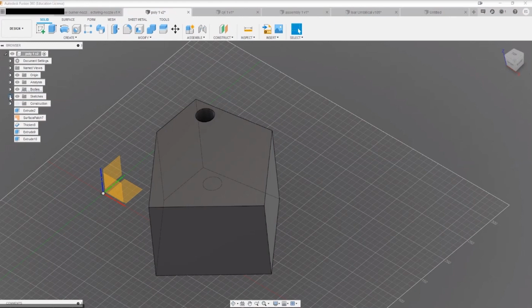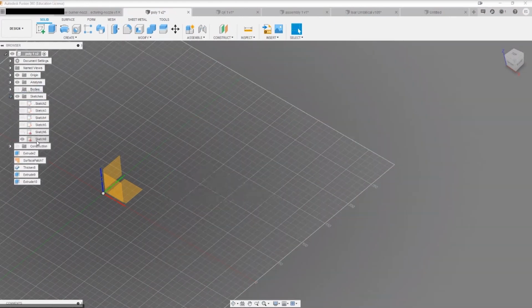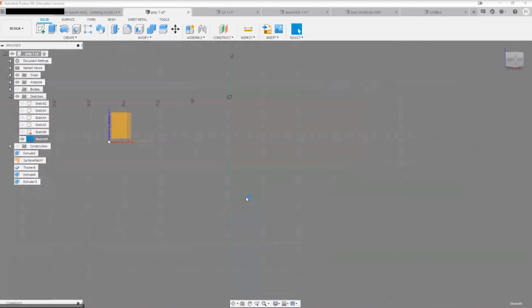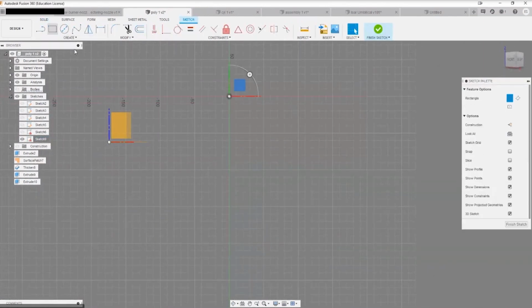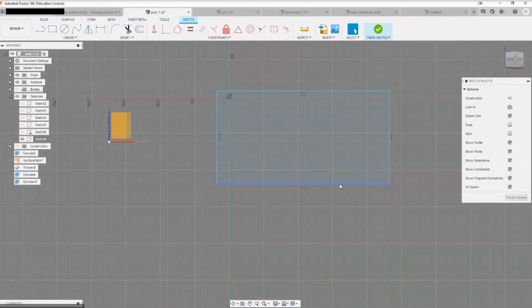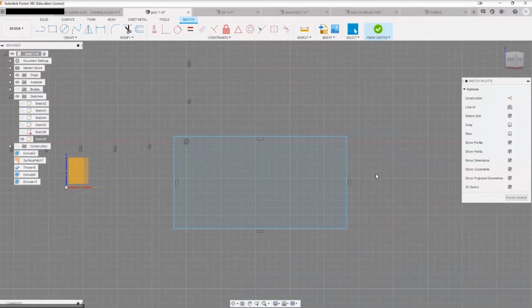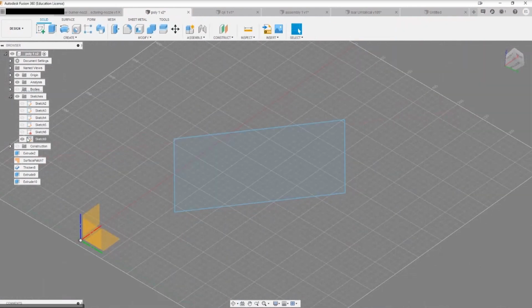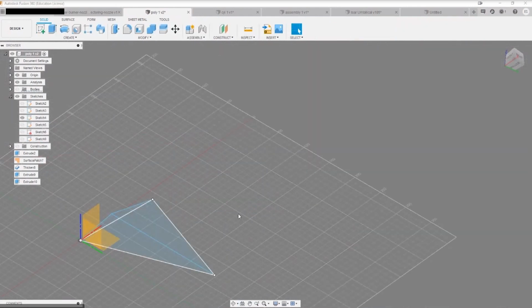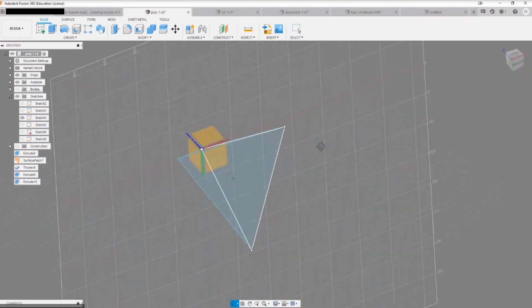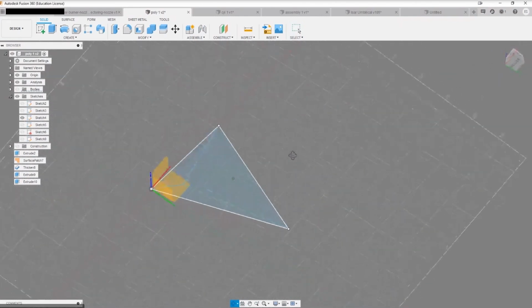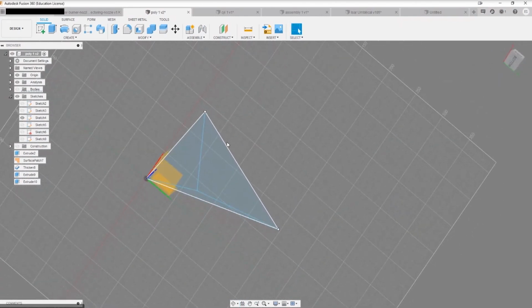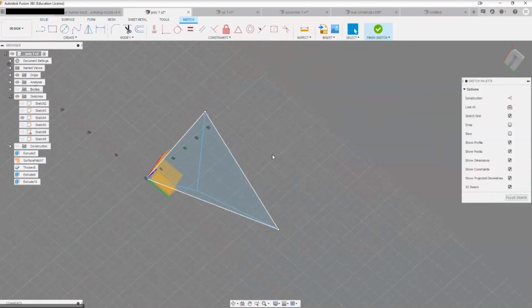And then the other thing is that say you're drawing a random line, and you mentioned you have the halfway point snap of a line, but if you want, say, the quarter way point, you don't have a snap for it. And if it's a really awkward number with a bunch of decimals on the end, instead of getting a calculator out to calculate that quarter point, you can just enter in the dimension box the equation, so the line length divided by 4, and it automatically calculates it. Yeah, that's a really good point.